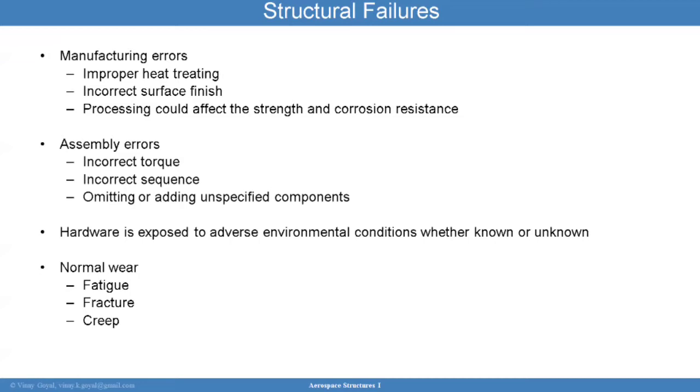Yet later in service, the surface finish becomes worse over time due to process controls that are getting lost. Well, guess what? A rougher surface finish can cause a crack initiation a little bit earlier in service, and perhaps that crack initiation can now drive a failure mode that was not foreseen before.